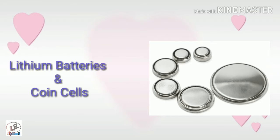Most of the lithium batteries are available in coin or button cell form. Coin cells are small discs and often lithium cells are used. Lithium cells are 3 volt, and similarly alkaline, zinc air and manganese are also used for button cells, but they are 1.5 volts. They are very small, very lightweight and great for small and low power devices, and they are very safe since their internal resistance is very high. They have a long shelf life and are fairly inexpensive, and they are not rechargeable.